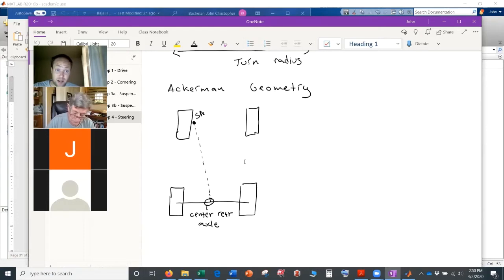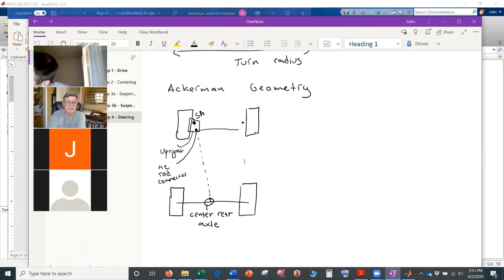So in the old buggy days, you'd have some upright here. And what you do is you connect your steering arm. So this is your upright, and this is your tie rod connection. And this will connect onto a bar that comes onto here. So you have a steering axis here. It does this on both sides, right? And if this bar that you hook up connects at a point along these lines, you're going to naturally get Ackerman steering.